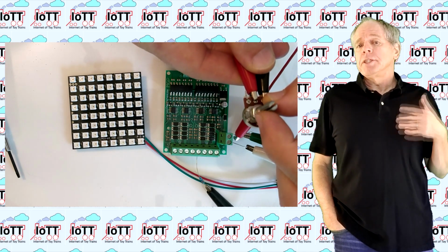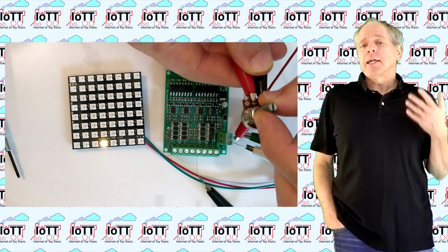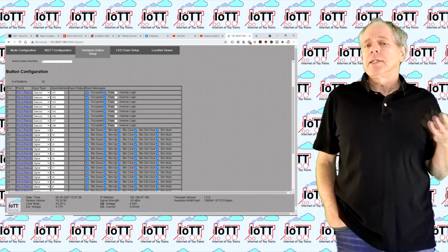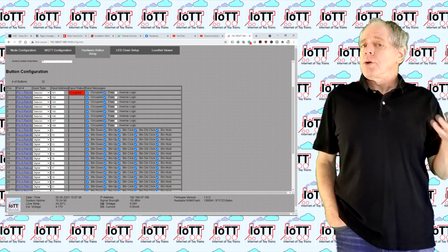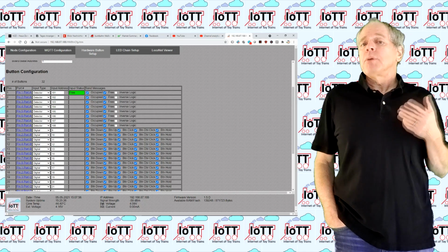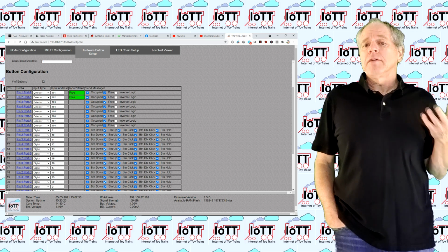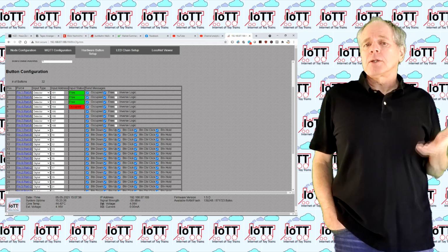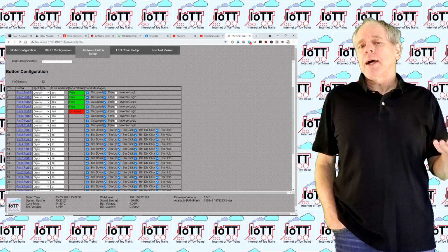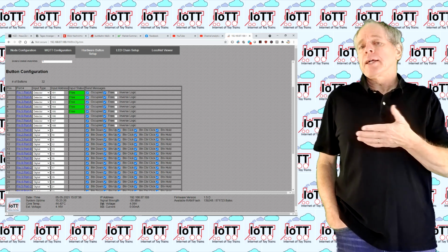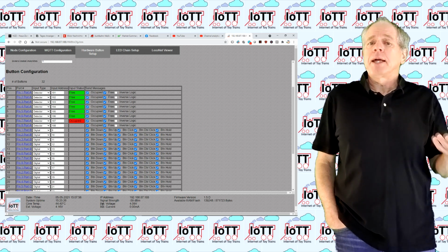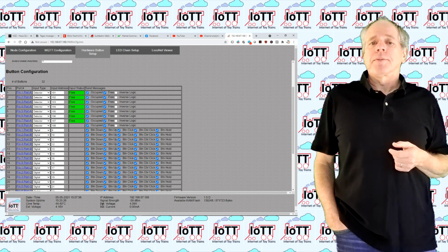For example, when using the yellow hat, it can send input information from the 32 input lines either as button messages, turnout position messages, block detector messages, or even analog values. Those messages are broadcasted over Loconet and can be used by any other node to trigger actions or calculate, for example, a signal status of an ABS system, and much more.